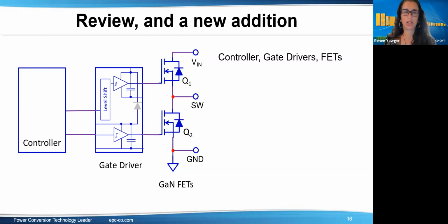Do you have any numbers in terms of minimum dead times that we've been able to achieve in a half bridge at higher current ranges, like around 40 amps? In that kind of range, typically around 10 to 15 nanoseconds is what we put on our evaluation boards. In the lab environment, you can dial things down so you can have almost no dead time, but that's just one board. And if the temperature changes in the gate driver, or you get a second one, or something happens, that's kind of dangerous. So we like to allow the margin.